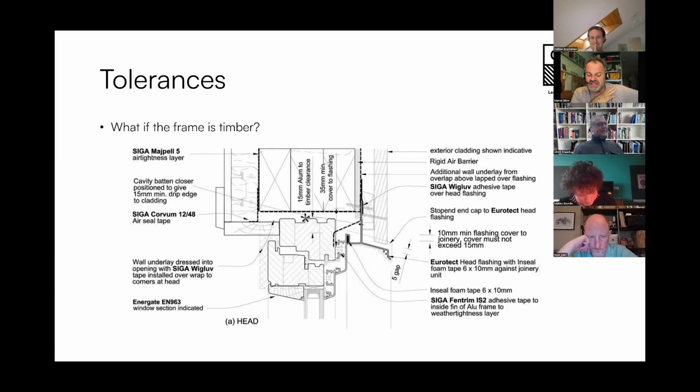But they are very fast. And they are able to make it almost press fit into it, and then they just need a little bit of seam. Very fast way of doing it. I would not propose this as a standard, but I've seen it, and with just a little piece of wood, they can easily shave it on site to the tolerances of the opening that was done by the contractor. Really crazy idea. For me personally, I don't want a piece of wood in between the concrete and an aluminium facade, for instance, that in case of water damage will swell and create other problems.